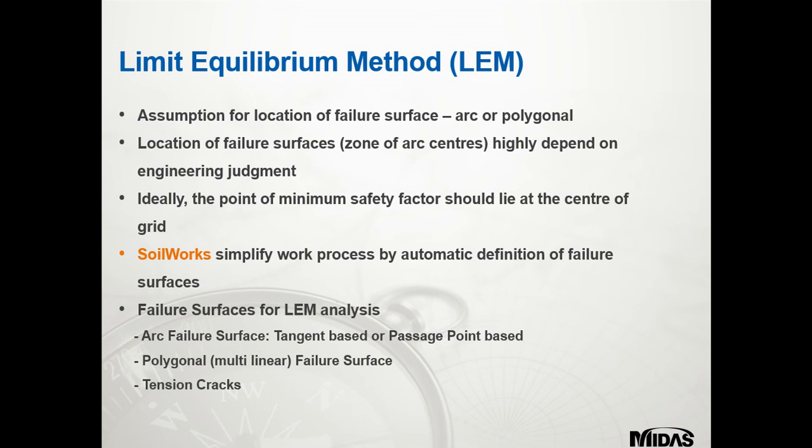SoilWorks can simplify this tedious task by automatically defining the failure surface. The various types of failure surfaces and situations can be considered for the LEM analysis. And the arc failure surface, the arcs are drawn based on tangents to grid points or passing through a critical point. The polygonal or multi-linear surface and the tension cracks, particularly are partially or fully saturated. So i.e. the actual tension crack created in the surface of the slope when water seeps into it.